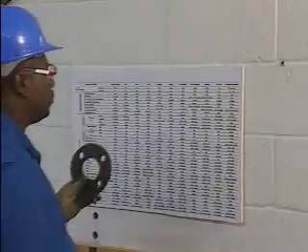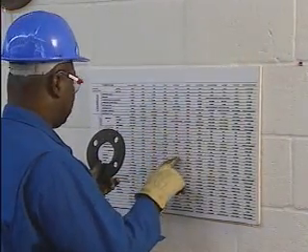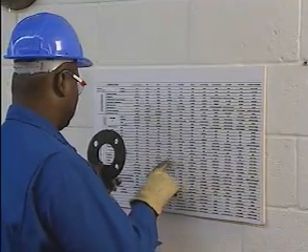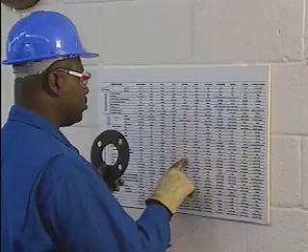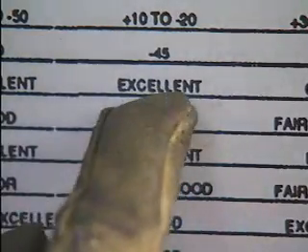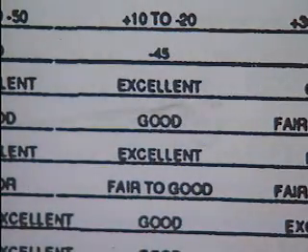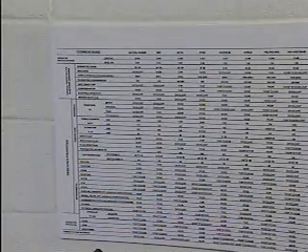A more comprehensive source of information can be obtained by consulting a physical properties chart. This type of chart, provided by most gasket manufacturers, rates the physical properties of common gasket materials. Each material is rated according to a list of criteria that indicates how the material will react under certain conditions. The information can help you determine the full range of applications for which a gasket material can be used.